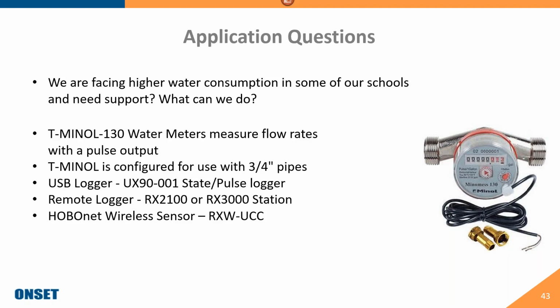Again, one of the nice things about having a generic pulse input is that, let's say you have a BTU meter, or you have an ultrasonic meter, or you may already have a water meter that already has a pulse output on it. You'd then be able to hook up any of our data loggers to that.